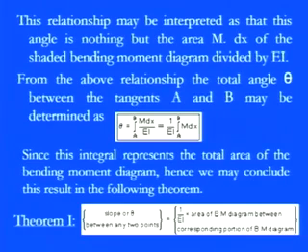In any thermodynamic process, the work done is equal to P dV. Whether it is an isochoric process, an isobaric process, or any other thermodynamic process, we simply draw the PV curve, the constant volume or constant pressure process, and whatever area comes under that curve gives you the work done, because work done is nothing but the integration of P into dV.